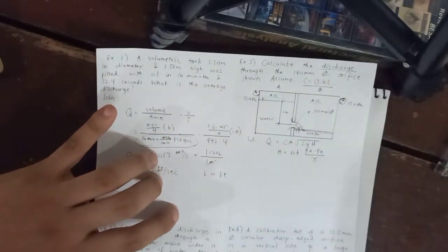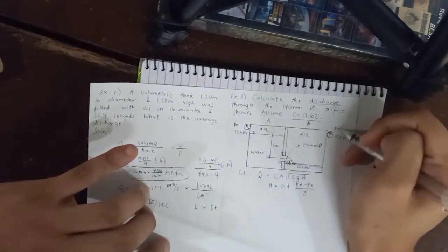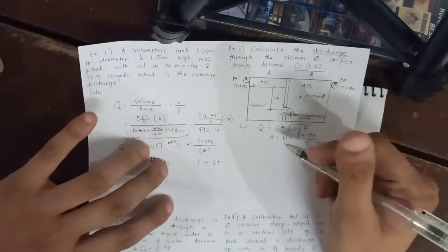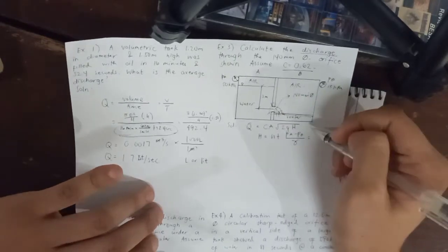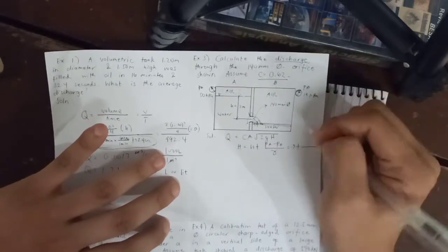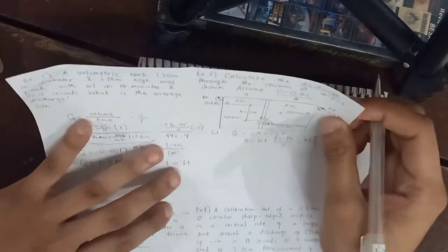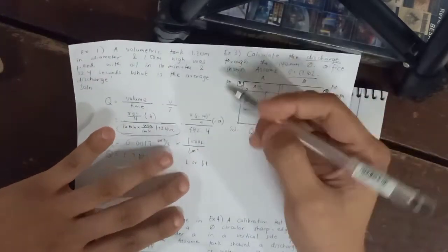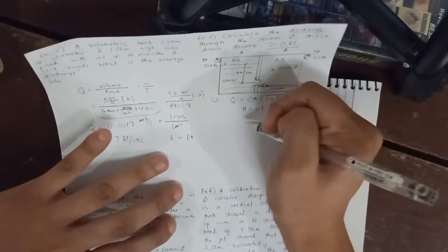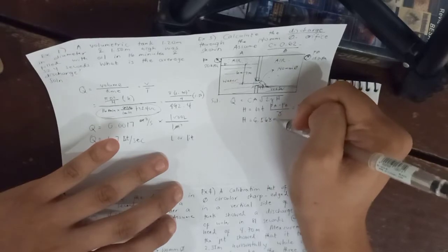So again, we subtract the two pressures, small p sub A and small p sub B. So easy na lang, because we have the values. This is H now: 3 plus the pressures are 50 and 15 over 9.81, the unit weight of water, this is only water. So our capital H, or total head, is 6.568 meters.